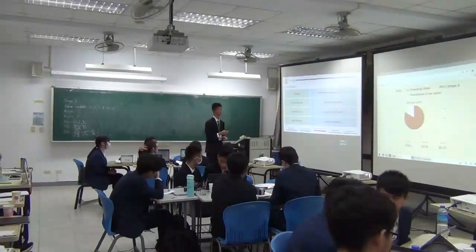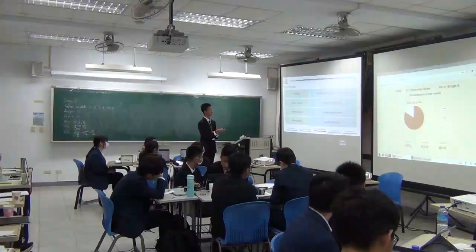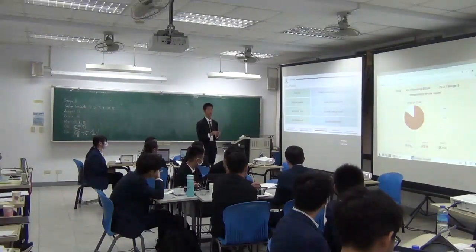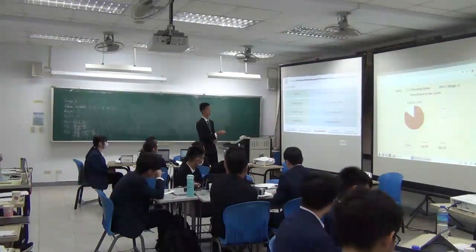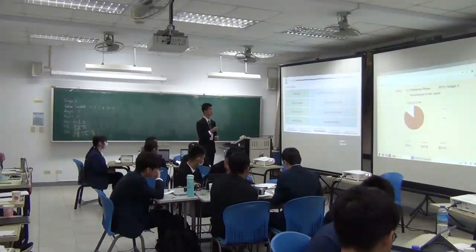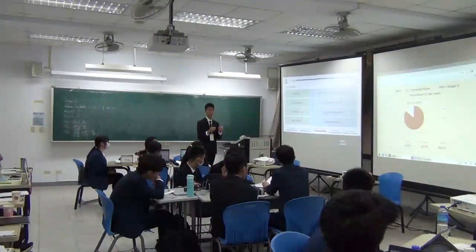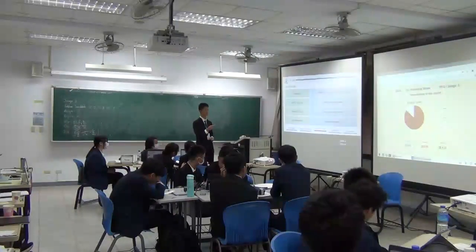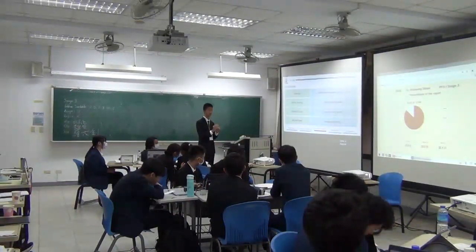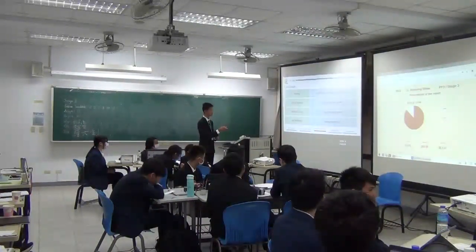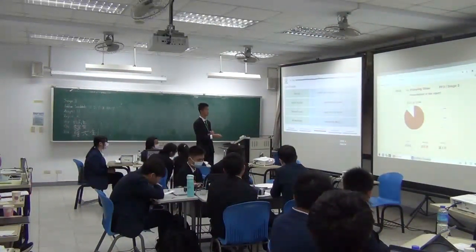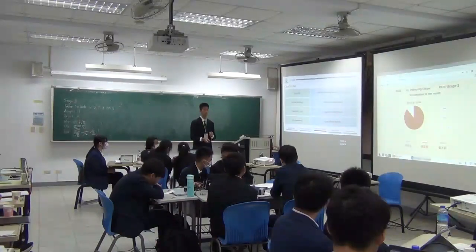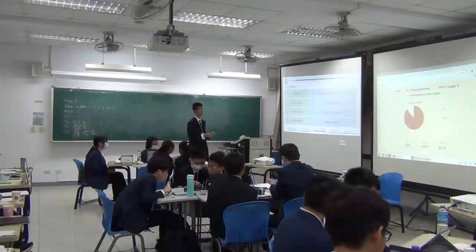So here is a conclusion of different factors. For viscosity, if there is viscosity, the pumping speed will be smaller, which means the exit velocity will be smaller. However, this is insignificant. Now for surface tension, if there is surface tension, then the pumping speed will be larger because the surface tension pulls the water segment upwards. Now for Bernoulli's law, because it predicts a pressure difference, and the pressure is higher at the bottom and smaller at the top, if we consider Bernoulli's law, we will get a larger pumping speed. Now for air resistance, which we only approximated, it will cause a shorter range, which we measured experimentally, and we corrected it based on experiments.